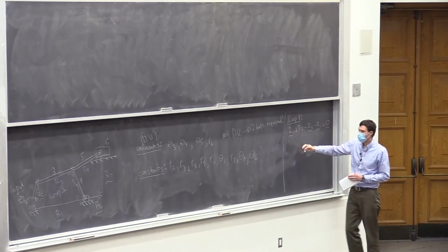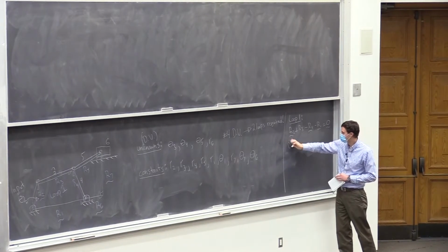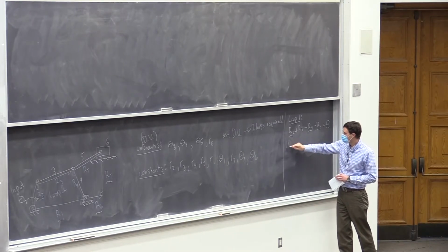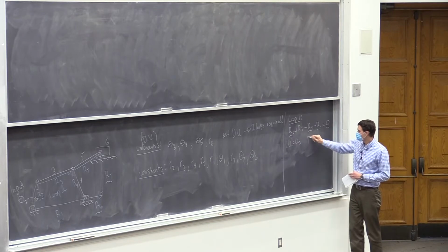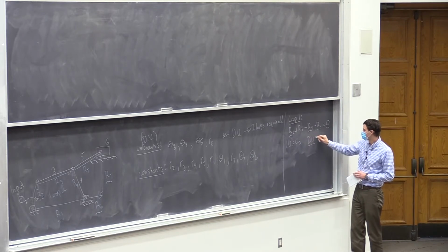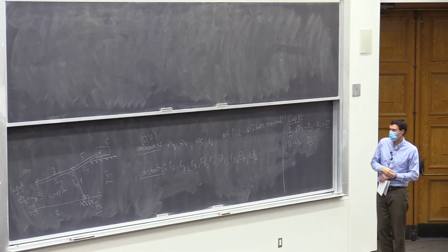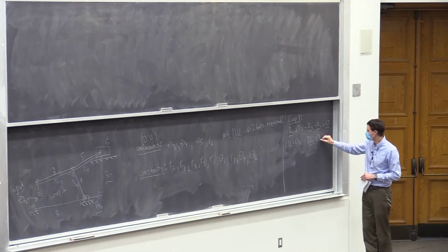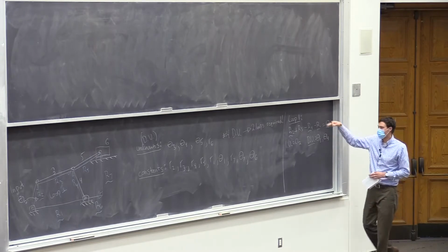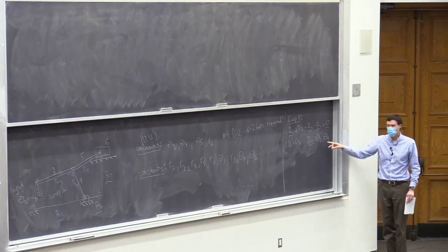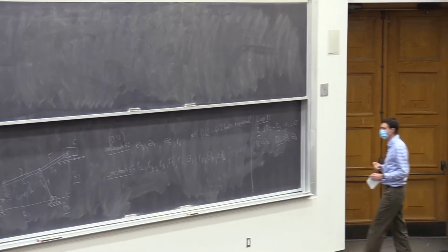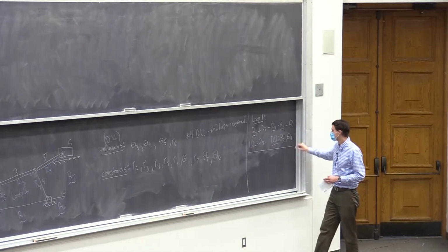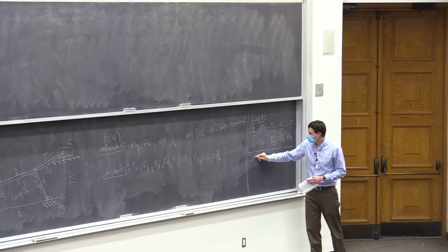Oh yeah, so loop 1 is going to have independent variables, the input is theta 2. And dependent variables, the unknowns, those are going to be theta 3 and theta 4. So you'll have 2 equations, horizontal and vertical components, and the two unknowns, theta 3 and theta 4. So you'll be able to solve that by itself. And now we can design our loop 2.